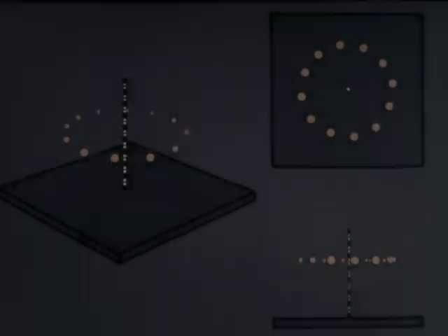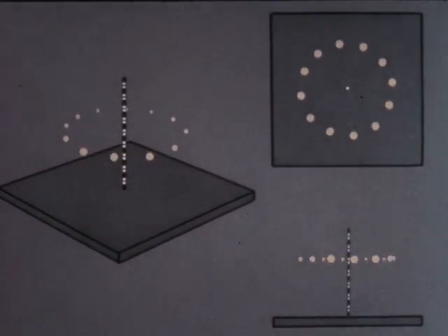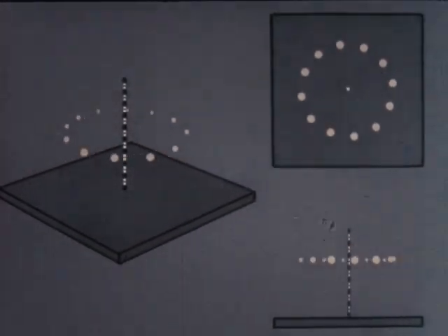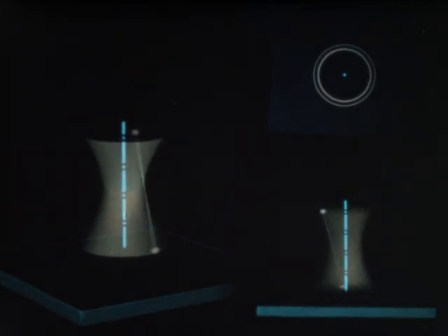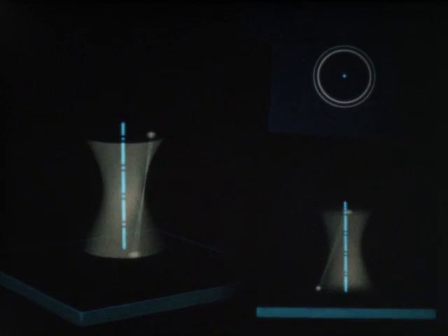In summation, the basic principle in all revolution problems is the control of a point as it rotates about an axis. A line revolves about an axis, with each point of the line moving in a circular path. The plane of this path always maintains a right angle relationship to the axis of revolution.